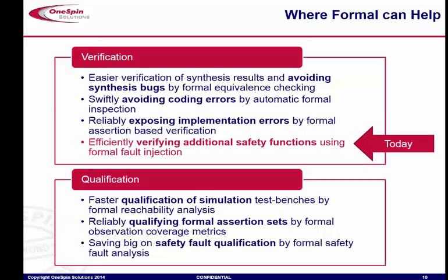Then, if you look at the human errors, formal is a well-established way to make sure that you get a very good functional verification on your RTL side already. But formal can also play quite a role in what I would call the core safety verification, where you look at the safety functions that you have implemented and whether these safety functions do a proper safeguarding.